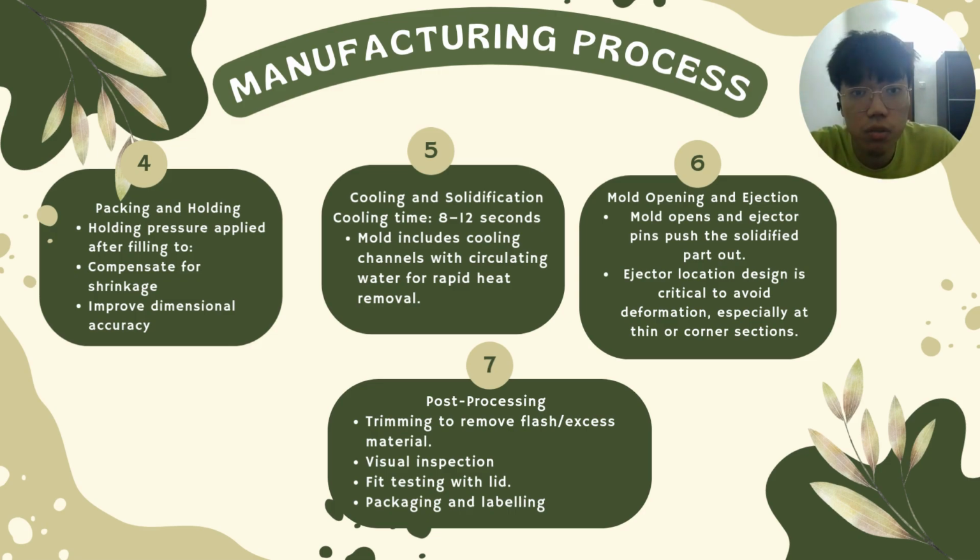The fifth is cooling and solidification. The cooling time is 8 to 12 seconds. The mold includes cooling channels with circulating water for rapid heat removal. The sixth is mold opening and ejection. The mold opens and ejector pins push the solidified part out. Ejector location design is critical to avoid deformation, especially at thin or corner sections.